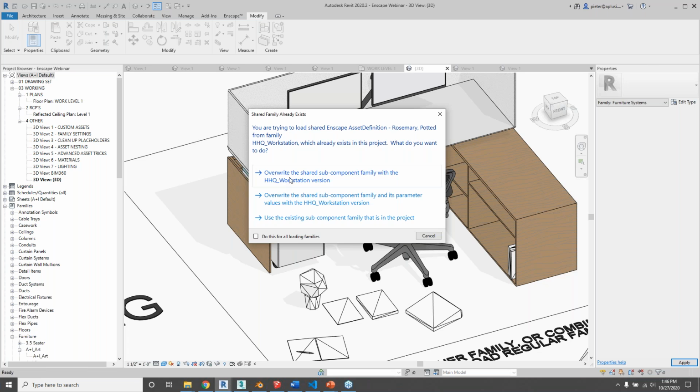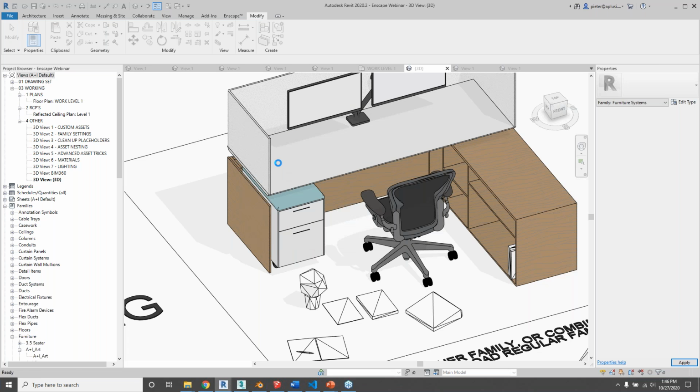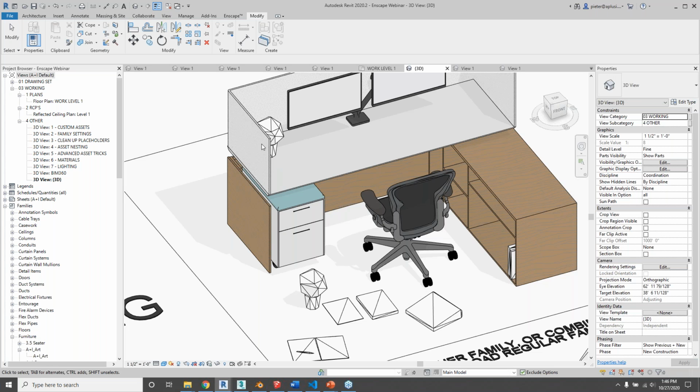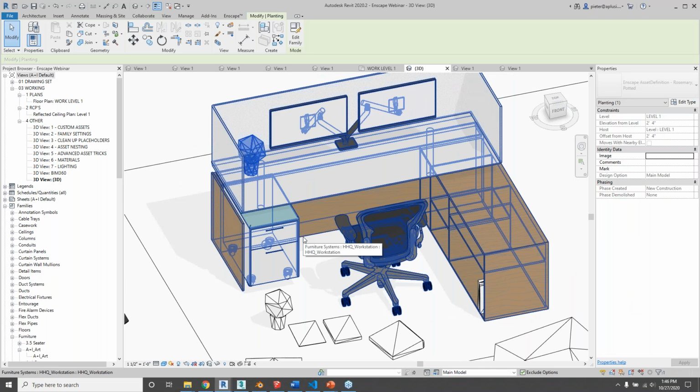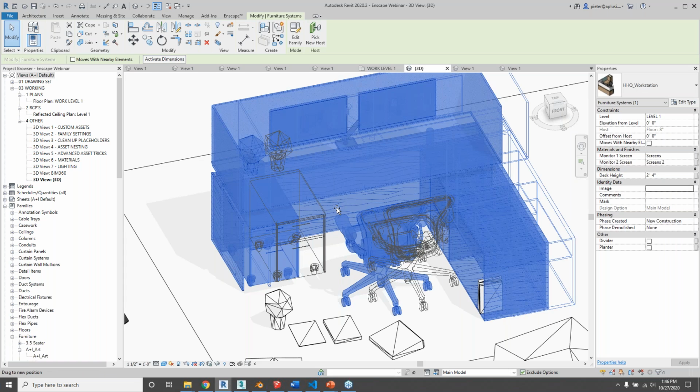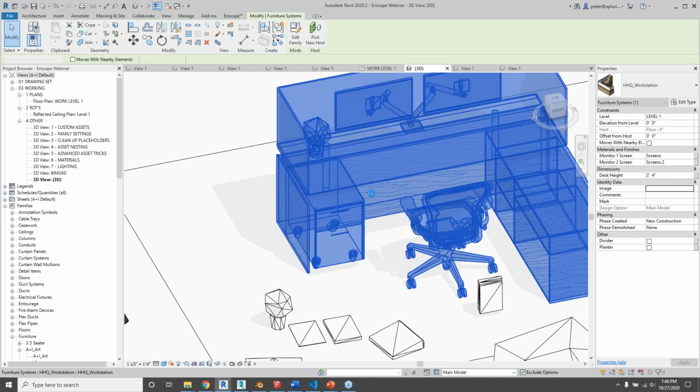And that is a sign that a family is shared nested. And so in Revit land, that means I still want to consider this its own little object with its own little parameters, like it exists in its own right. It will schedule, it will tag separately, all that stuff. It's just that it's nested in this family, so it moves wherever that family goes. And if I hide the main family, the nested family hides, stuff like that.